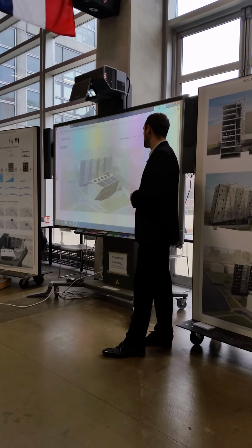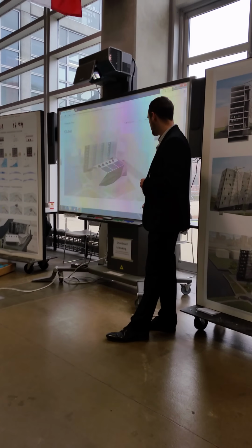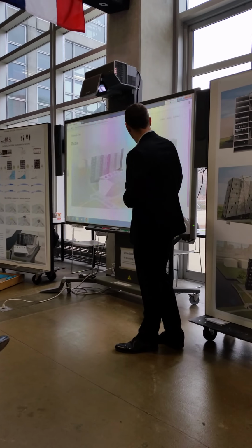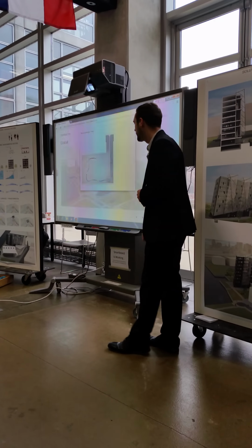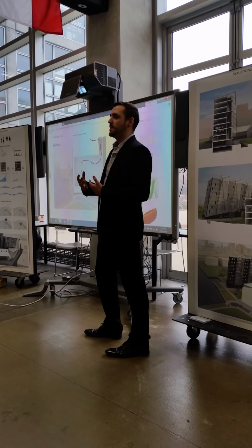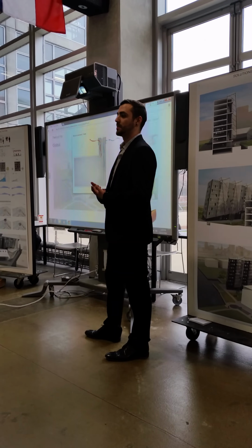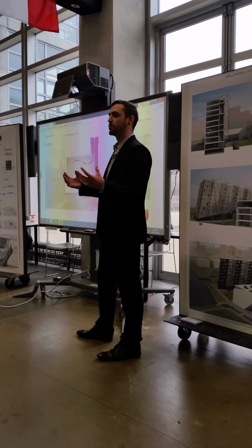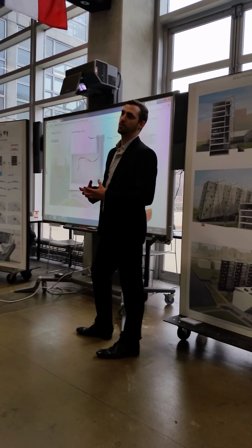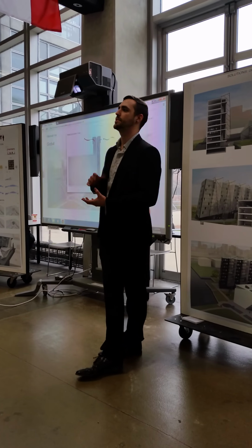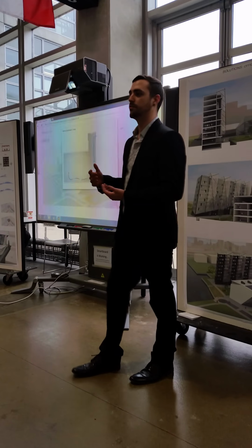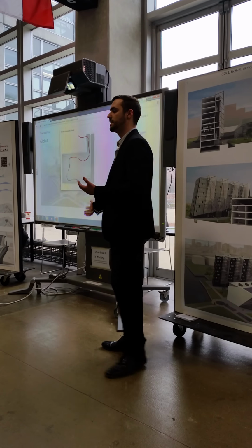And then moving on to the atrium and lab space. The atrium space would probably have the highest mechanical load in a typical building because it has the most concentrated amount of people or occupants. So it generates the most need to be naturally ventilated.